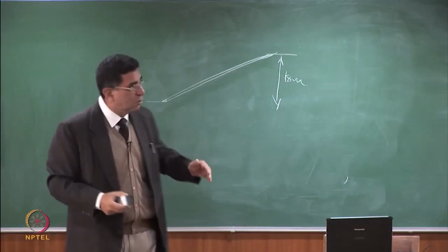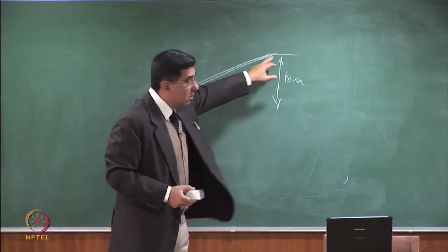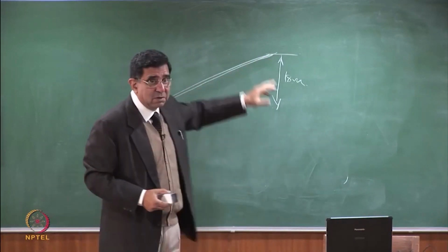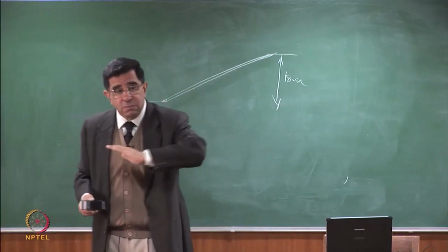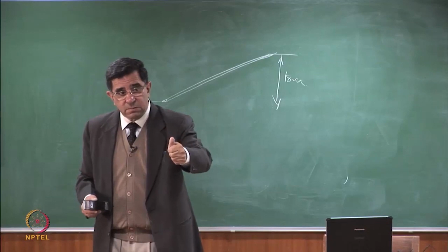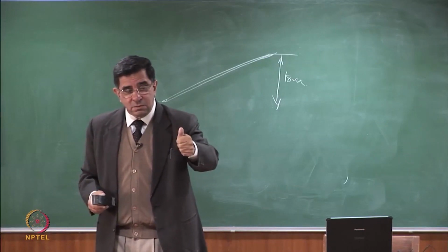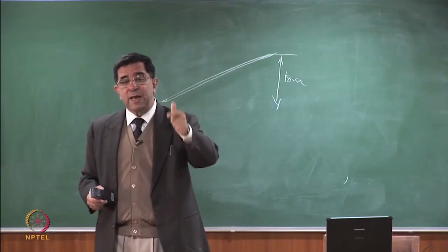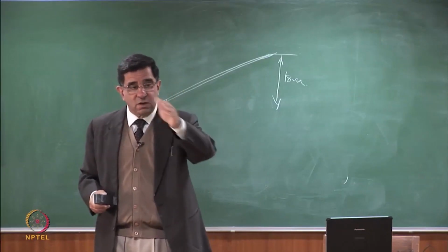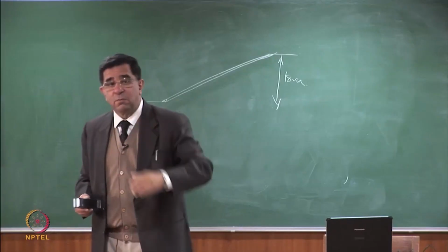You will never find a slope of an 18 meter high embankment like, suppose it is 3:1, this is 50 meters. There will be no continuous slope of 50 meter length in any landfill. Why? I've already told you this. You basically need berms primarily to break the speed of the water of the surface runoff. And then we use those berms also for making pathways for maintenance.